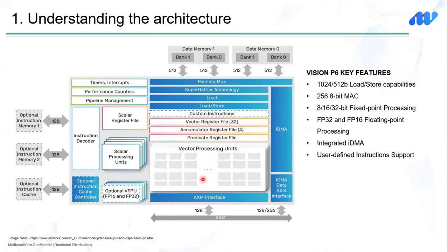The next main component to look out for in any architecture is the memory subsystems. It's important to understand the various subsystems available as part of the memory, including instruction cache, data cache, scratch pad, and data memory. We should try to understand the sizes and characteristics of these components, which will enable efficient data access and management. Next is the local data memory. For example, the P6 architecture does not have a data cache. Instead, it utilizes two local data memory units along with the IDMA engine. Getting to know these components also helps in optimizing data movement and utilization.